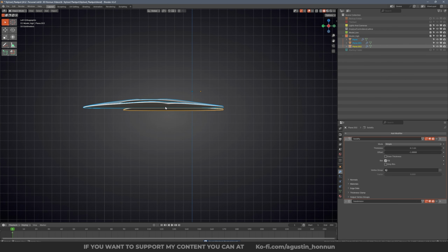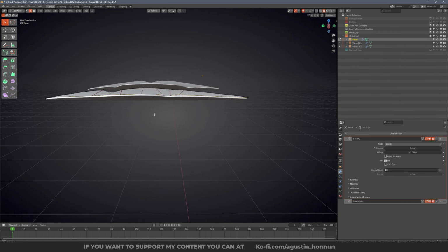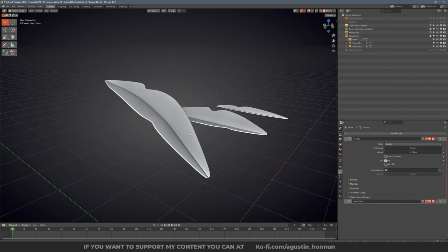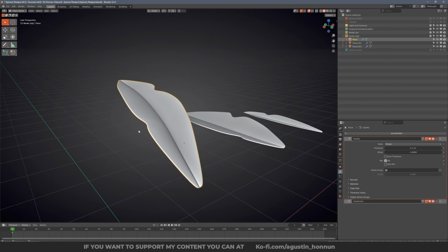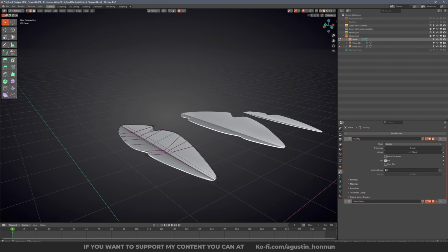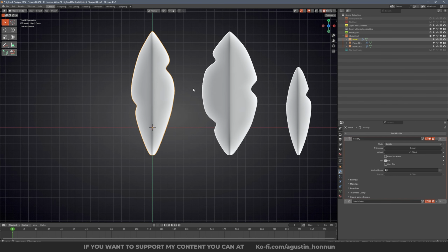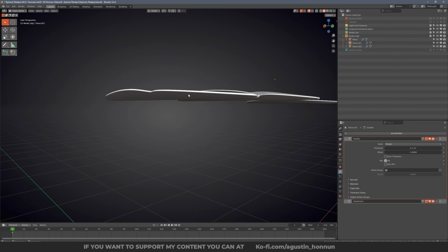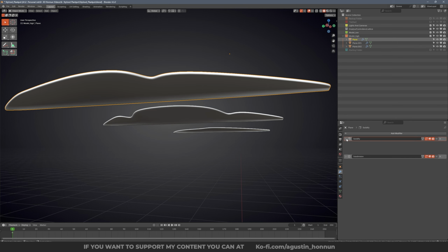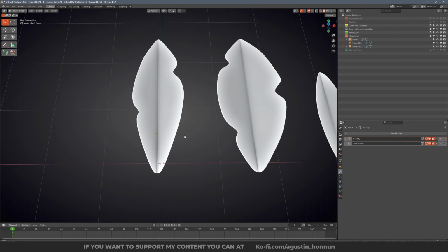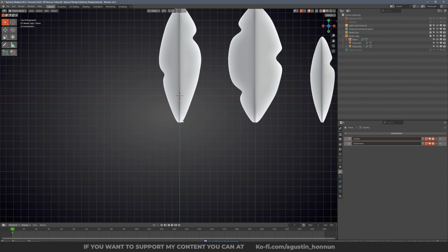You can add the curvature here or bending the leaf like this, but this time I'm not going to be doing this right now since we can do this later. First we can texturize all of this or simply use them as 2D shapes. Maybe the solidify modifiers not necessary, but for now I'm going to be using it like this.